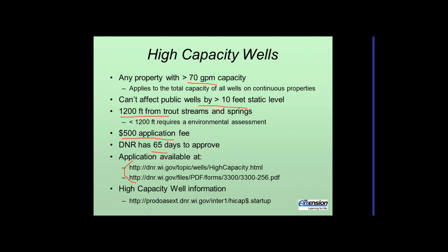And if you want to see what kind of wells are in your area, this last link lists all the high capacity wells in your area, and you can sort them by county, you can sort them by irrigation well or type, but it'll list the wells, the depths. So if you're looking at putting in a well, you can get a good idea of what the depth of that well might have to be